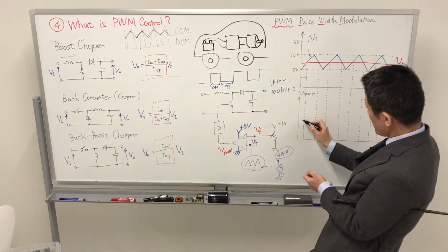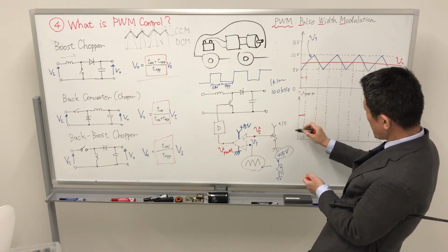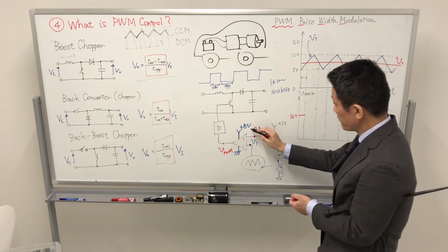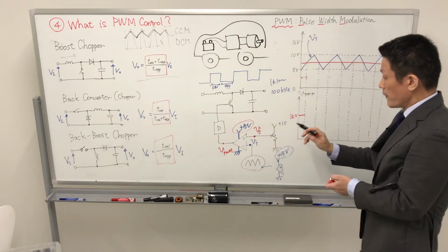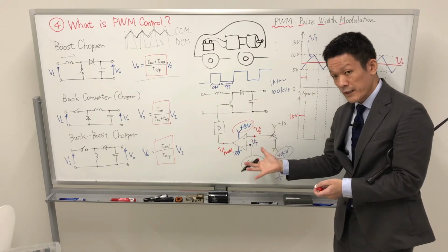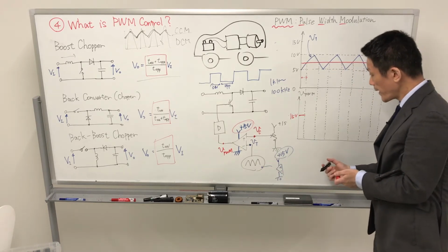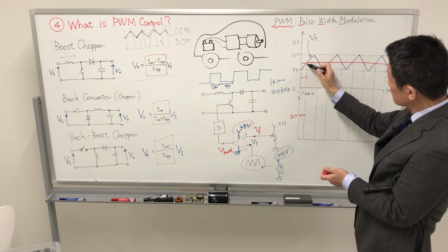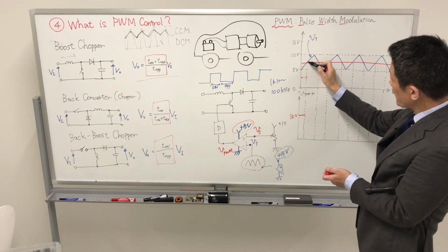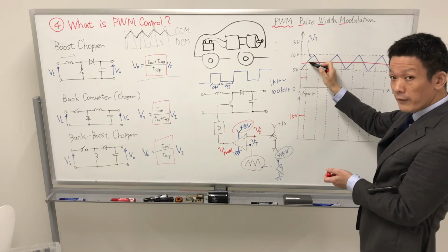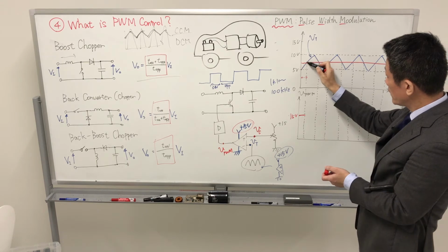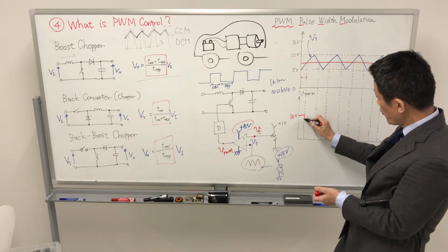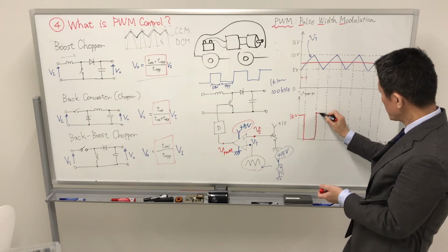So the output voltage is plus, and the plus voltage is 15 volt because we use 15 volt for the comparator's power source. As the triangle waveform increases like this and takes over this point, this one is the minus side. So: upper side, lower side, upper side.